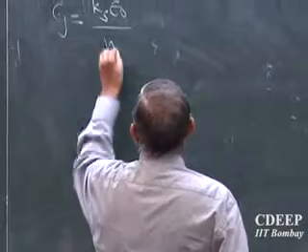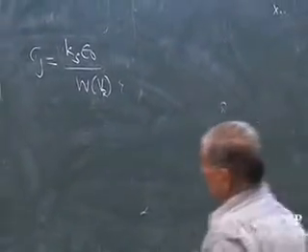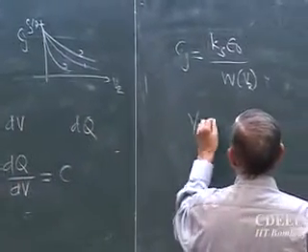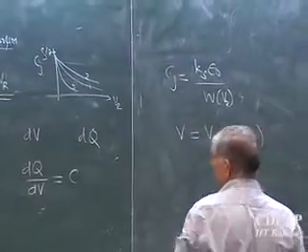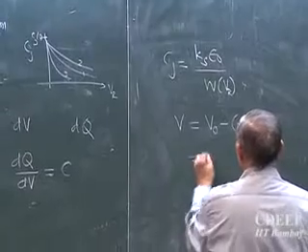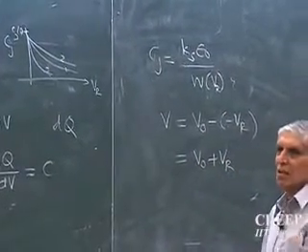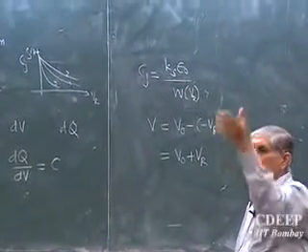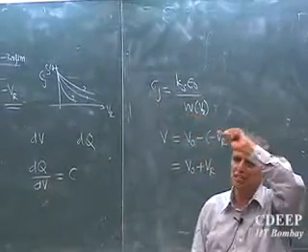Just to give an idea, this is a function of VR. If you see this potential now from this graph, the V now is V0 minus of minus VR. Two batteries, essentially they will add. Both are in the same sense, so the voltage on the battery will get added by the applied voltage. Please look at it, I applied reverse bias, both fields are in the same sense.